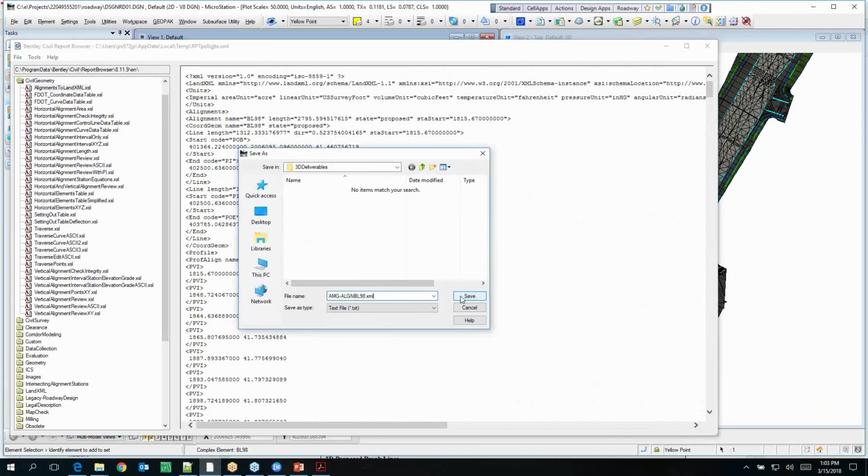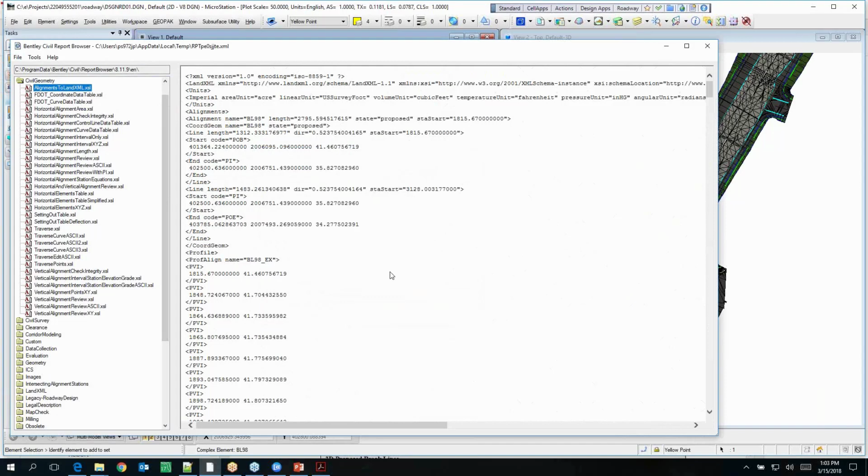So Todd, it doesn't work if you do save as XML. I guess I haven't tried that. It doesn't read the right format. It's not the right formatting, is it? It's an HTML XML versus a LandXML. LandXML 1.2 applies additional conversions that it shouldn't be doing. Yeah. Okay. Experience. So make a note of that in your book that you don't save XML as text.